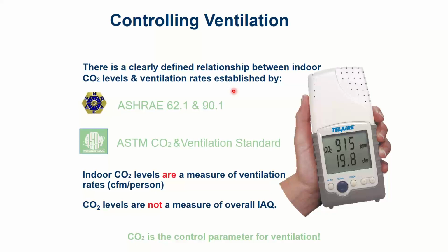The way we determine how many people are there is CO2, because people exhale CO2. You suck oxygen in, you exhale CO2. If I measure the CO2 in a room, it's kind of a surrogate way of counting how many people are actually there. You should know that CO2 is not considered a pollutant. It is not harmful. I mean, it's coming out of your face. You're the one putting it in there.